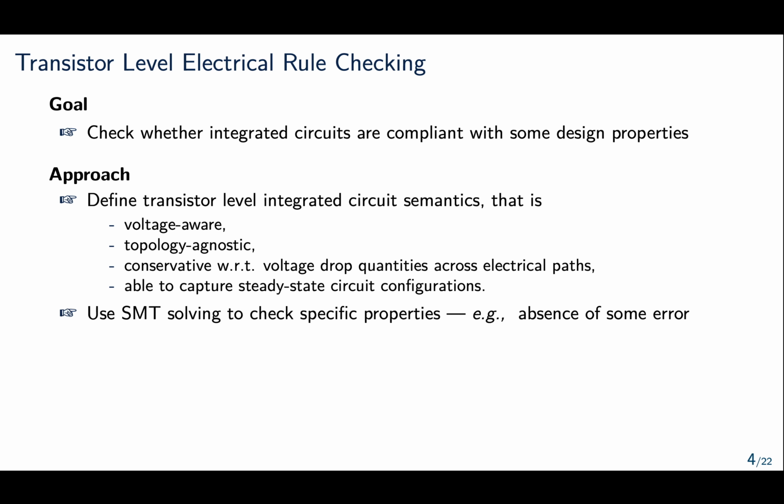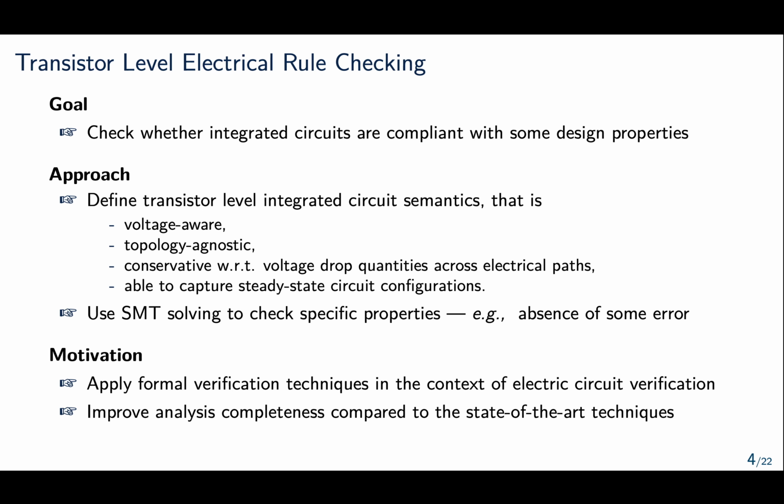We are going to use SMT solving to check specific properties. SMT here refers to Satisfiability Modulo Theories. In other words, we write a logical formula with booleans and numbers, and we use some SMT solver to check whether it is satisfiable. The motivation behind this work is to apply formal verification techniques in the context of electric circuit verification and improve analysis completeness compared to existing techniques.